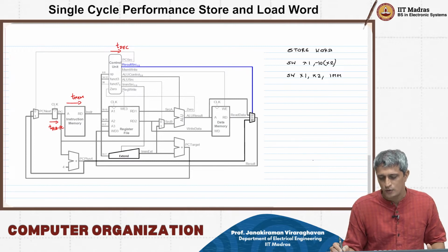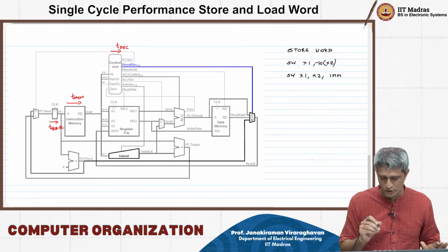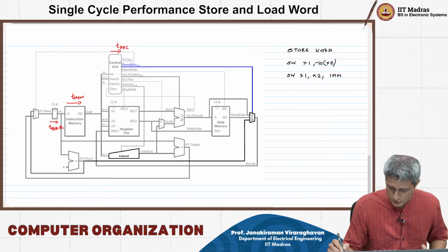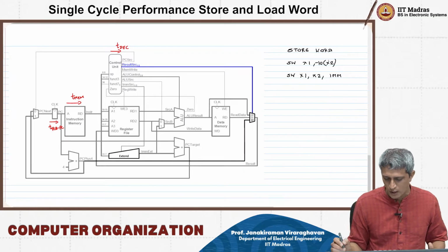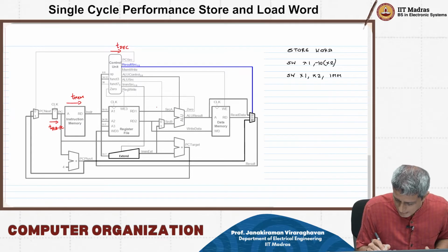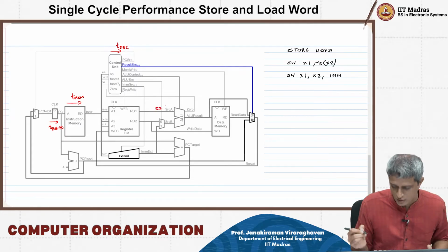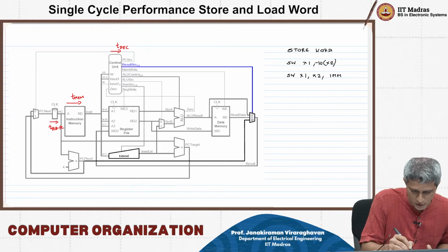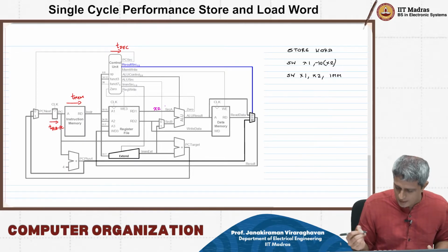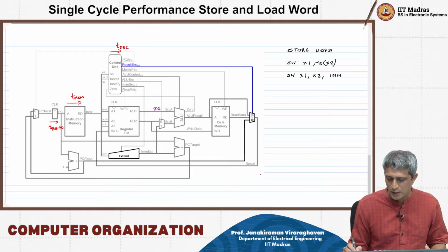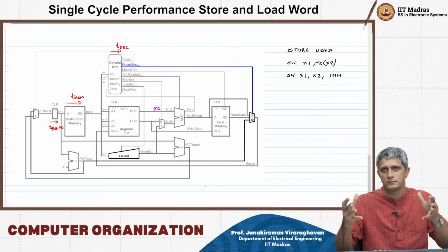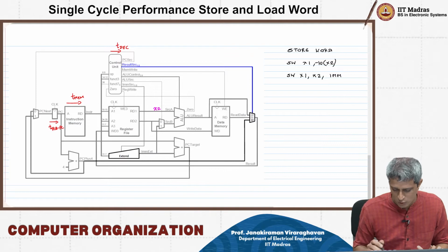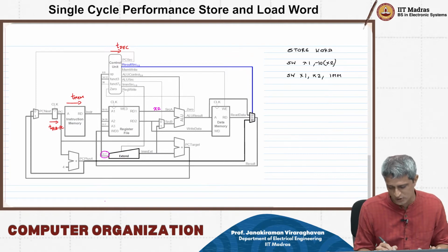Right, and so let us look at this operation. We are going to get the value of x2 here, which is going to appear at this point, right? So maybe I'll put this in magenta or something, x2. And this immediate data minus 10 is going to come as some 12-bit number that is going to sit here, this 31 to 7, right?